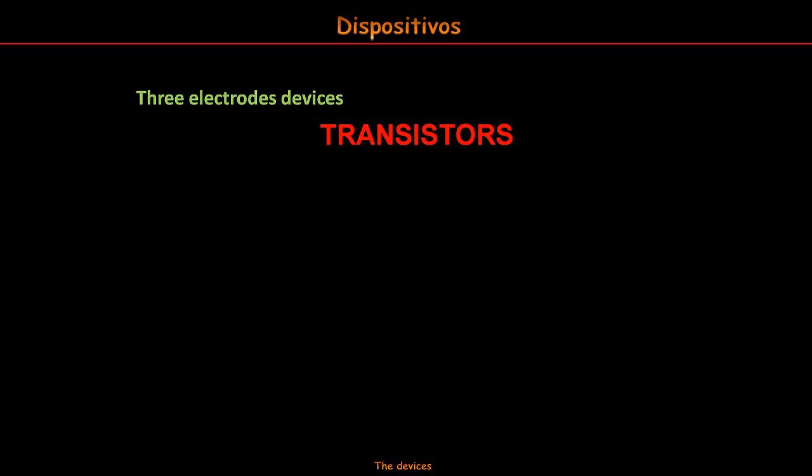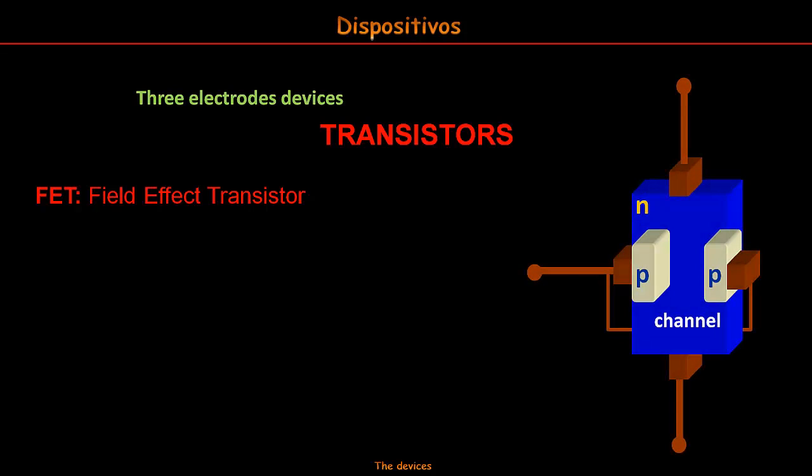There is another way to make transistors, using electrical field effect to control that flux. That is used in a field effect transistor. Here you are, an N-channel transistor of the junction FET type. An N-zone is the bulk of the transistor. Here it is. And two P-types, modifying the depletion zone widths of the junctions formed, make a real gate to control the flux of electrons upside down.